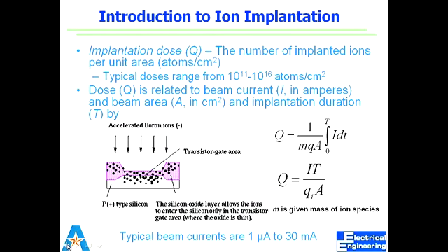Right? So that's fine for the top, but if you look at that particular feature, the oxide has a profile within the silicon itself. So I agree with you, we can pattern from the top, but it seems there is a pattern on the lower side as well, at the interface of silicon. I remember something called LOCOS process. Right? We have taught you that. So you have to remember that, because a week from now, I'll be examining you on those things.